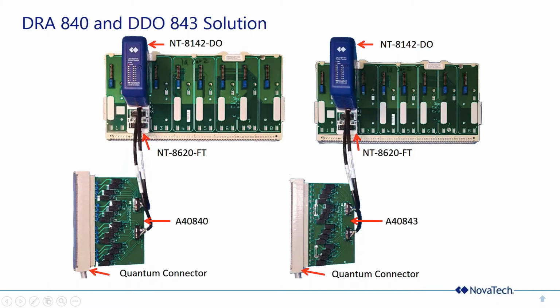These termination cards do all the signal conditioning necessary to convert the signals into a form that can be used by the card. So maybe there are 120 volts coming in, but there are 24 volt quantum I/O modules that we're talking to. So they're going through a relay from 120 volts down to 24.